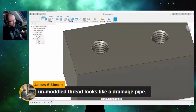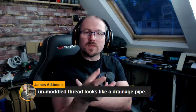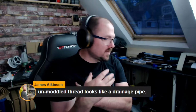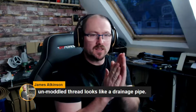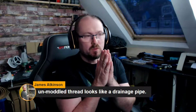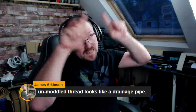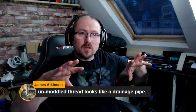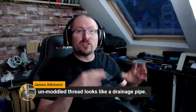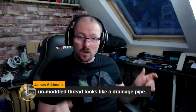Now, what I can't stress enough is that with your 3D printer, when you're making something, you need to allow something called clearances. Clearances are the physical space that you allow for an object to come in contact with another object. For example, if you imagine a door in a door frame, there is a physical opening that the door can fit into. You need to make sure that there is sufficient space, one, for the door to actually fit, and two, for the door to actually operate and open.